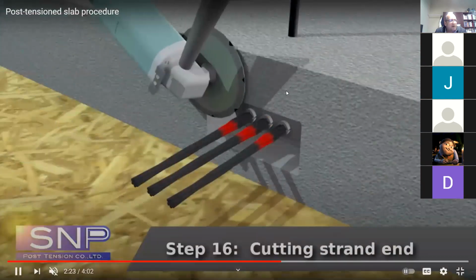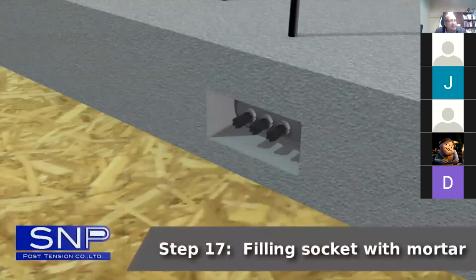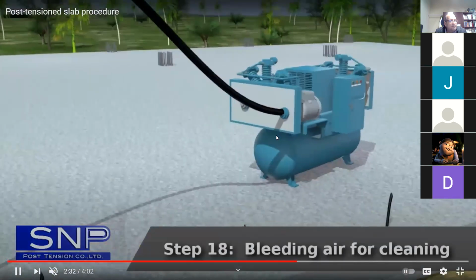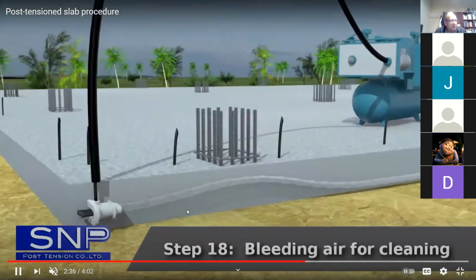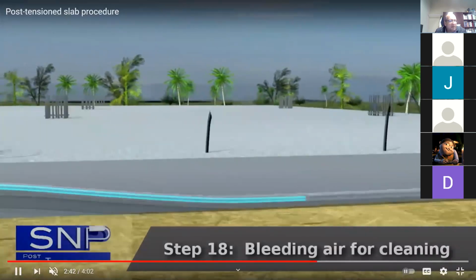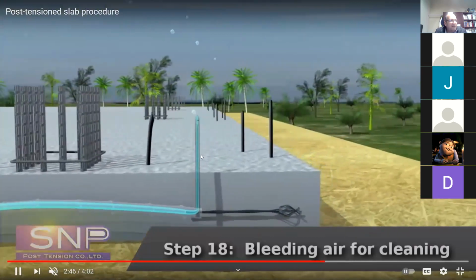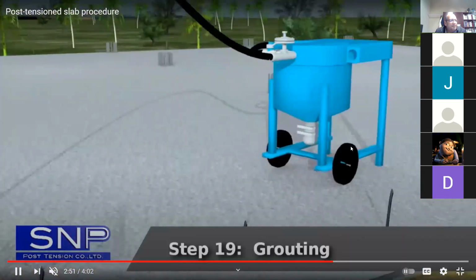Then after that, they come and cut it with the grinder, and then they fill it in with grout. After that, they start to grout here, to pump the grout through the hole. If you remember, they need to fill it with grout to be sure it's really solid. But first, they need to clean it, as it says here, bleeding air for cleaning, right? After they clean it, they start to fill it in with the grout.